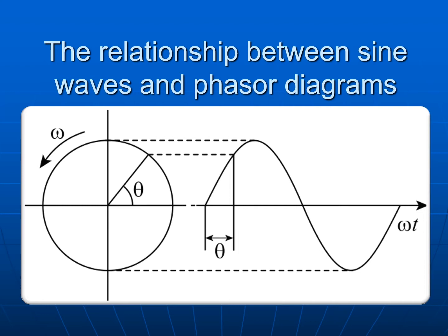If you remember, we discussed earlier what a phasor was, a phasor being a representation of the magnitude of an electrical property, and that property could be voltage or amperage. When we represent a phasor, that tells us how much of that current or voltage is there. And as we place that phasor on our circle diagram, representing 360 electrical degrees, the degrees tell us its relationship to another electrical property within the same circuit. So we could have a phasor for voltage and a second phasor for current, and the angle between the two would represent the time lag that we'd have between those two as well.